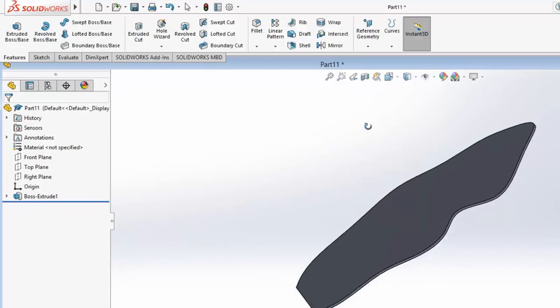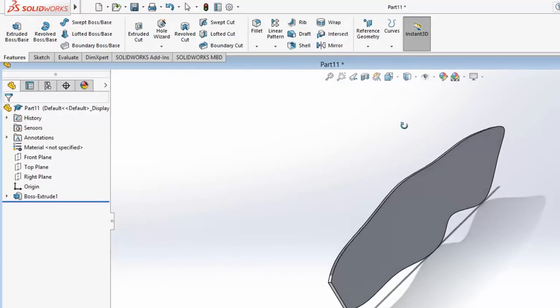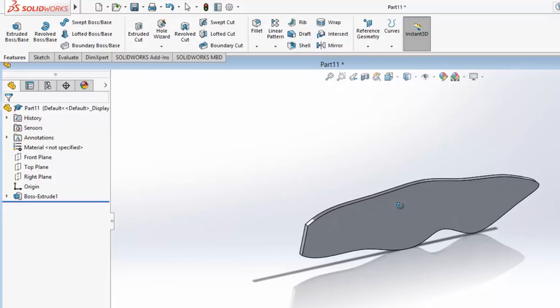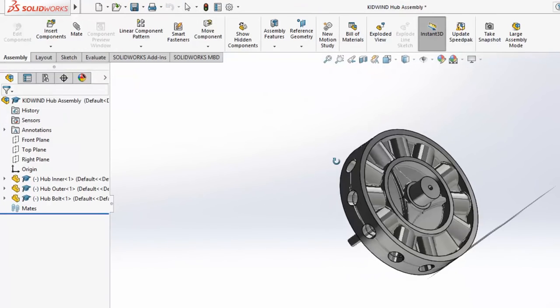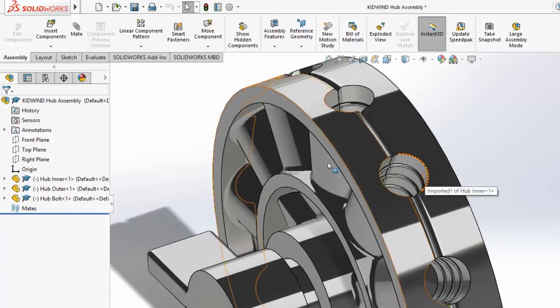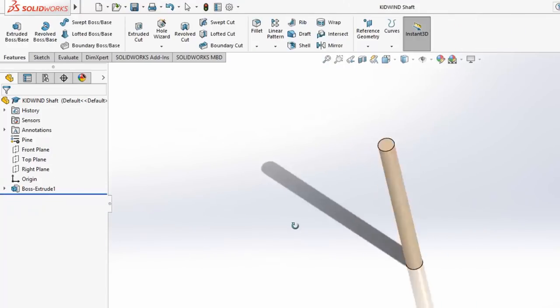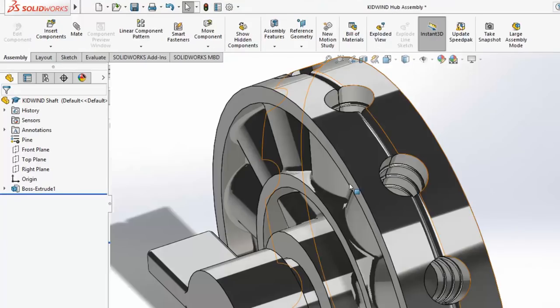Okay, so here's my wind turbine blade. It's pretty lame, I know, but it'll work for the example that we're doing right now. So one thing that I showed you guys in class yesterday is that all of the wind turbine blades that you make will be attaching to these plastic hubs that mount onto the generator, and those plastic hubs have inserts for a 1/4 inch shaft. So we're going to need to make a cut into our blade where we can attach a 1/4 inch wooden dowel. I'm going to show you guys how to do this now, and insert it into the hub.